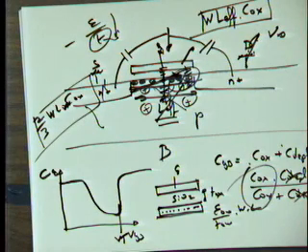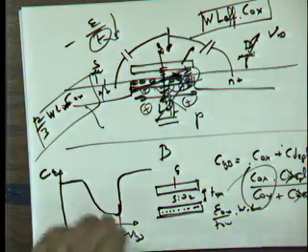Okay? So now there was a question about what should I assume? Again, it depends on how I phrase the question. In general, if I say you have to make sure that you take all the nonlinear effects into account, then obviously you have to figure out if the transistor is in saturation mode or linear mode, and you use the right values. If I say no, you can actually simplify, let's assume that the gate capacitance is WL times Cox, you're fine. So I'm going to once again make it explicit for you. Okay? All right, that's gate cap.